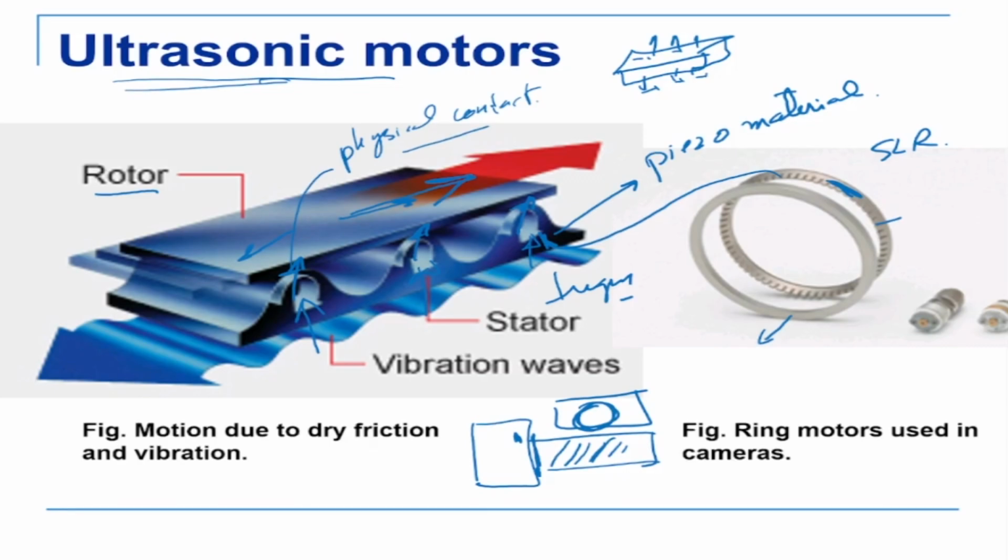Now, the advantage of these motors is that they are very strong. They are independent of the size effect, so you can make a very small ultrasonic motor and it will still work, because it is working on the piezo crystal. So with piezoelectric, piezo ceramic, you can make a very small one and it will still work, unlike a DC motor.